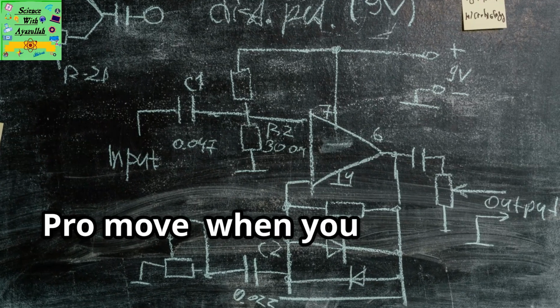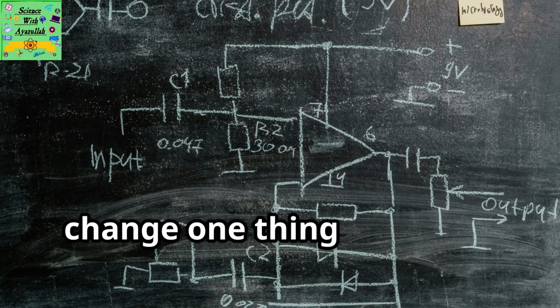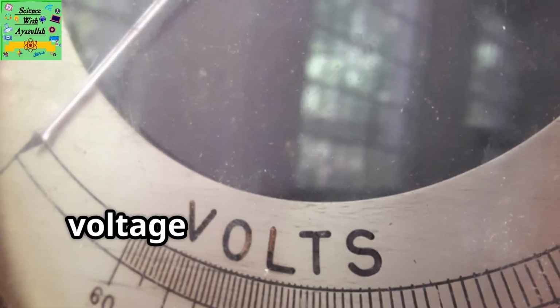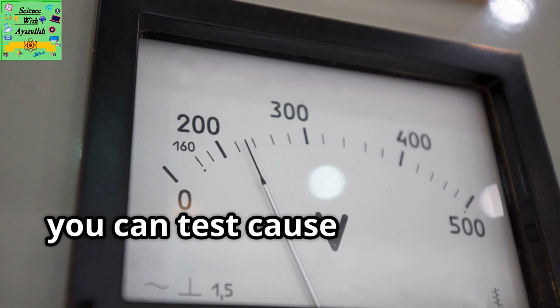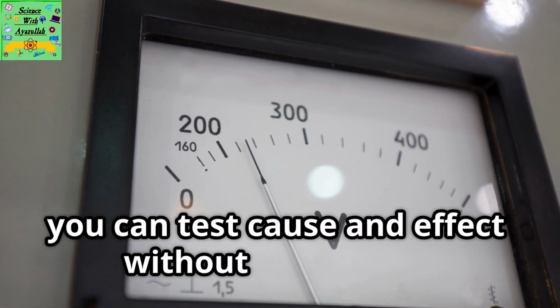Pro move: when you change a diagram, change one thing at a time and label it, voltage and component values, where you put the meter. That way, you can test cause and effect without guesswork.